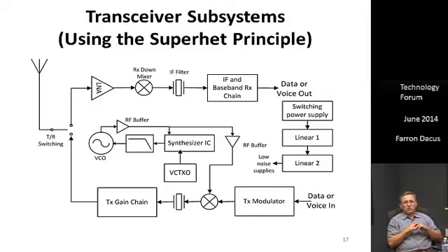Yeah. And the way is to use direct sequence spread spectrum and chip up to a higher chip rate, so you use a wider filter, but then you get this artificial noise bandwidth narrowing due to what they call the processing gain of the direct sequence. So it sounds real fancy, but basically it's just a way to get ultra narrow bandwidth.